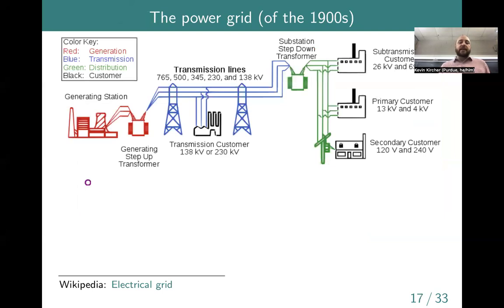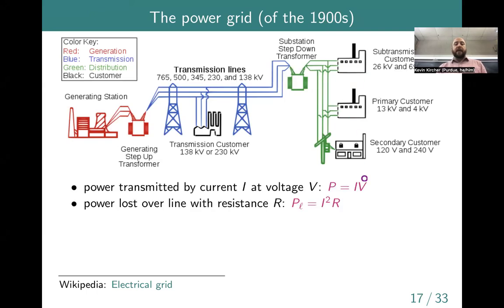Okay, so I showed this on Tuesday. This is, again, a sketch of the electricity generation system and transmission and distribution system that more or less is still the way that we do things today. And for most of the 1900s, this was the case. So again, we have a big generator, step up for high voltage transmission, step down for safe distribution, and then step down again for use at the edge of the grid, which is really where our focus is in this class.